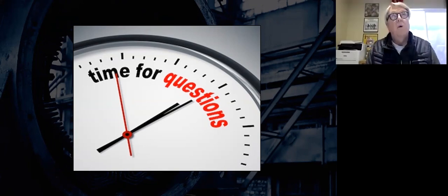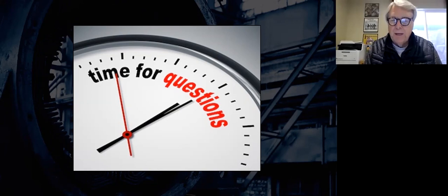Next question that came in is, how often does an arc flash study need to be completed? Now that's an excellent question. We discussed the fact that you need to train your people every year. Excuse me, every 3 years. Sorry, every 3 years. How often do you need to do an arc flash study? The answer is you must evaluate your system every 5 years.